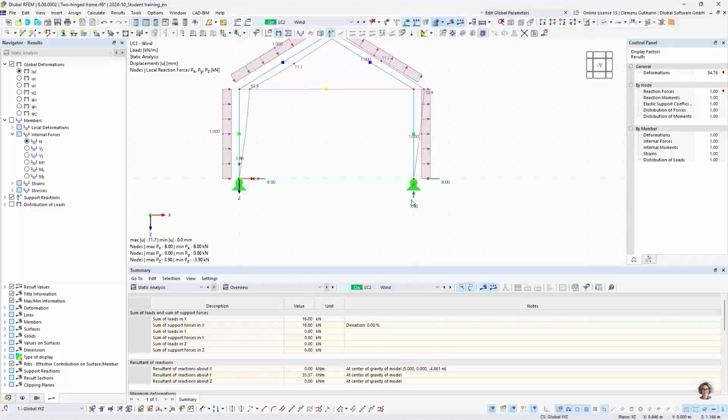And that leads to a force pair, being a compression support reaction on the right and a lifting support reaction on the left. So yeah, this is interesting because you might need to design the connection for the left side accordingly. So it can bear not only compression forces, but also lifting forces.